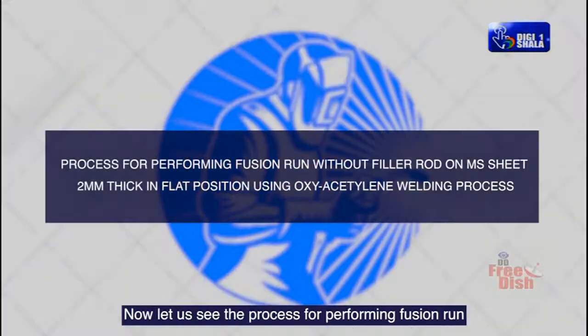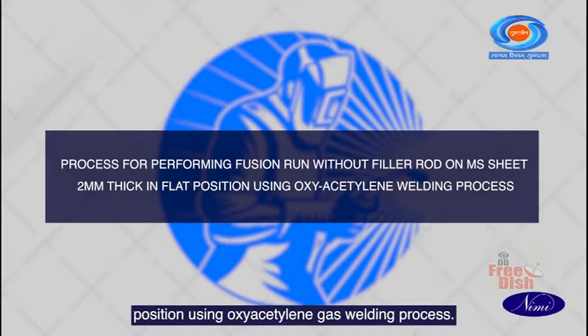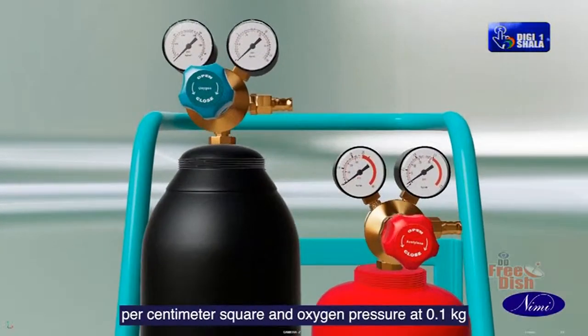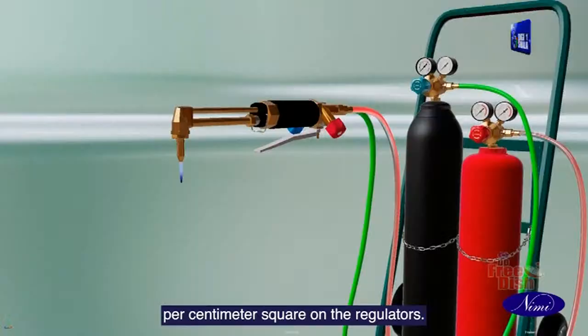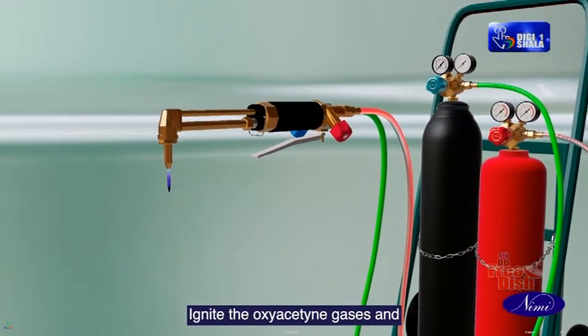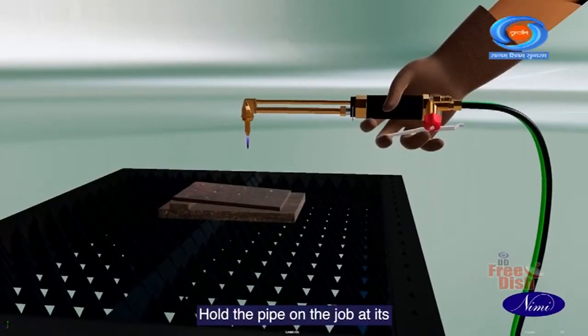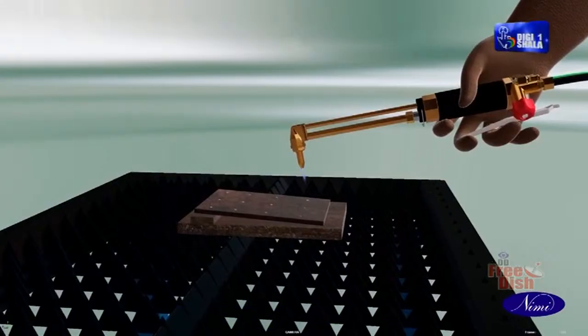Now let us see the process for performing fusion run without filler rod on MS sheet 2 mm thick in flat position using oxy-acetylene gas welding process. Set acetylene pressure at 1 kg per centimeter square and oxygen pressure at 0.1 kg per centimeter square on the regulators. Ignite the oxy-acetylene gases and adjust the neutral flame. Hold the blowpipe on the job at its right hand end at the required angle.